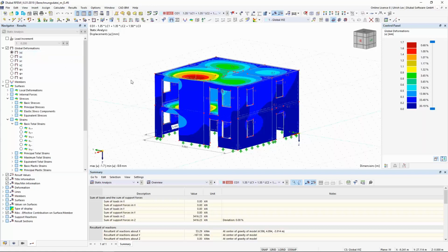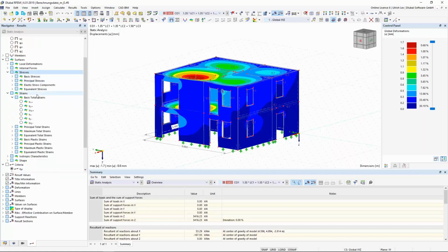There you can find maybe input errors or something else. Especially for the masonry material, you can then check the stresses, but the stresses cannot be higher than they are defined in the material model. So it's maybe more interesting to take a look at the strains.